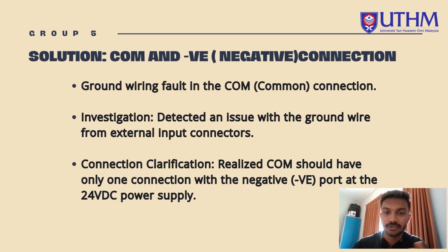So yes, there is a solution for the problem. Ground wiring fault in the common connection. That's the problem investigation: detect an issue with the ground wire from the external input connectors. Connection clarification: realize COM should have only one connection with the negative port at the 24 VDC power supply in the training kit.